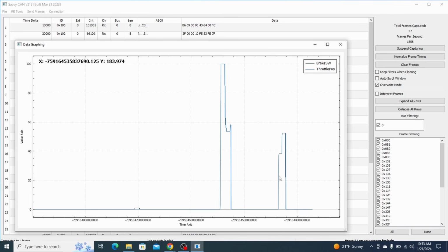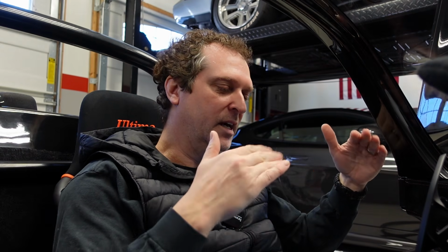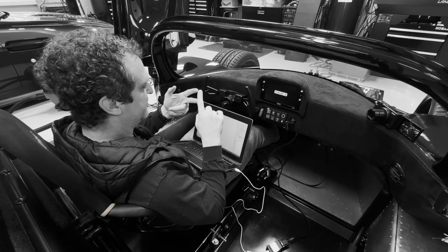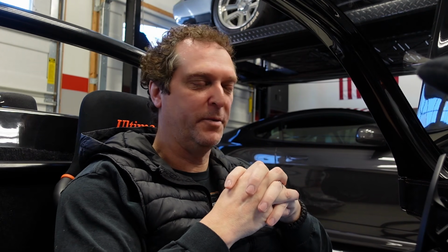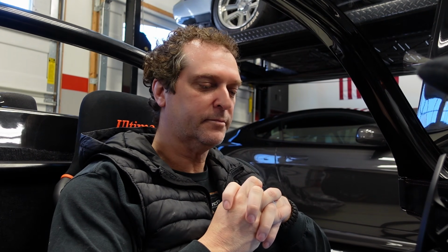So we'll get to that here in a little bit. But that's the thing, you start to find these patterns when you're playing around with this. And again, based on the frequency, that'll narrow you down into certain areas, and then grouping attributes together, critical ones like brakes, throttle, RPMs, those are typically on the same CAN ID. And we'll confirm that once we get to RPM.